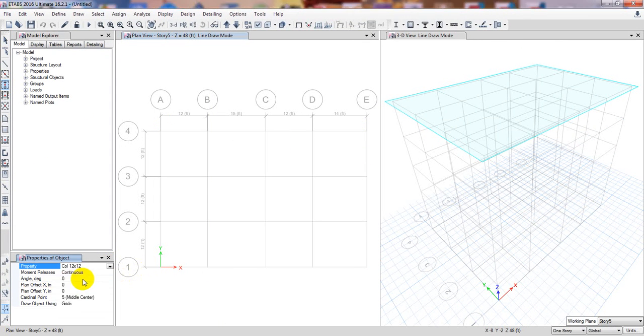So column 12 into 12, because we know that on that side the loads are low. I mean we need the minimum size of column, because here loads are very less. On that side we will consider only the load for that structure, and that is only 1/4 of that slab load. Okay, so I'll just give it here.